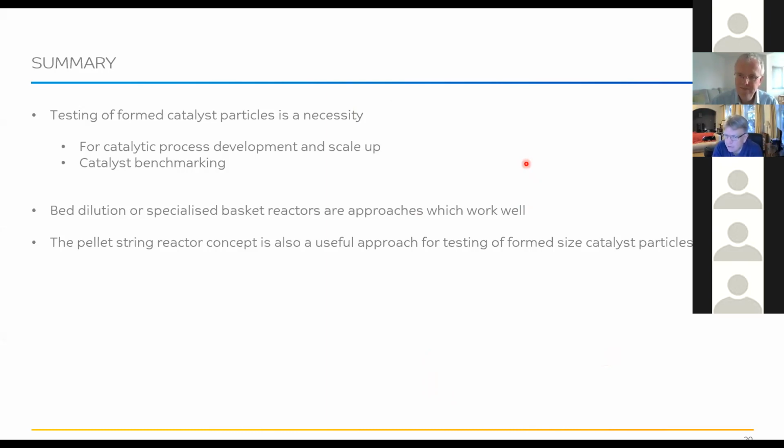Are there any external mass transfer resistances, and how does one account for them? Well, in the example I've given in the methanol synthesis, yes, absolutely there are mass transfer resistances. What I'm therefore looking at is the effective performance of the catalyst accounting for that mass transfer resistance.